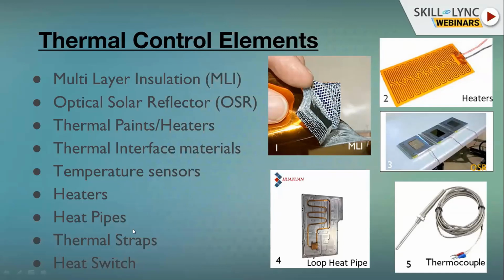Then we have thermal straps. Thermal straps are flexible straps which are used to transport heat from one component to the structure, to dissipate the heat in the structure.